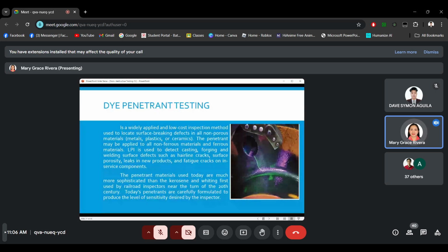Okay? So the main purpose of this test is to examine the product after casting, forging, and also the weldments. And in order to detect different types of defects like hairline cracks, surface porosity, and then we can also detect if there is a leak in new products, and also if there are fatigue cracks on the in-service components.